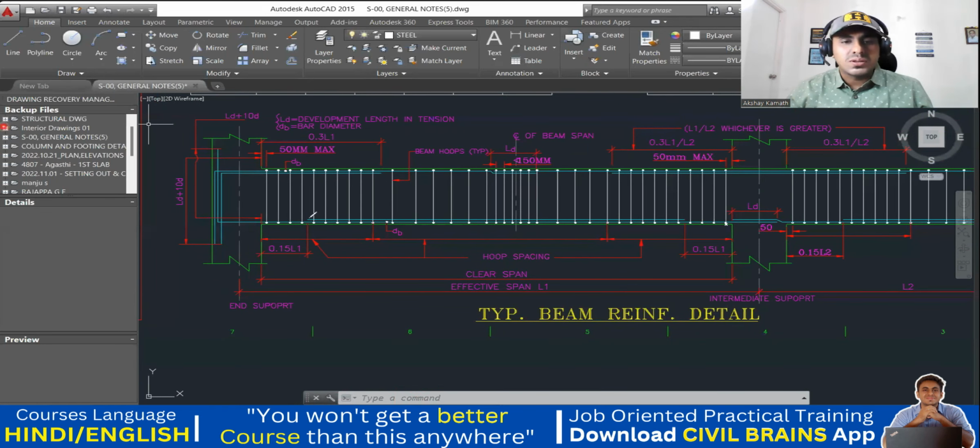The last thing left out is your bottom curtailment bar. Till what distance does it have to stop? From the face of the column, you leave 0.15 into L1. Suppose it is a 10-meter span, 0.15 into 10 is 1.5. From here, you leave a gap of 1.5 meter. From here, you leave a gap of 1.5 meter. And then this bottom curtailment bar will go up to here. Understood the concept? Chalo.